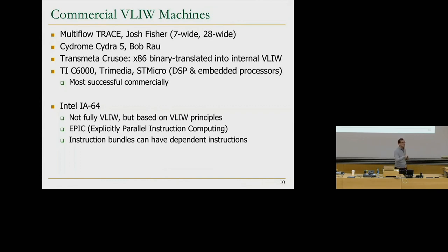The compiler tells the hardware, okay, I'm sending you 8 instructions per cycle, but look, between the 4th instruction and the 5th instruction, there's a dependency. Now the hardware can actually see that, decode that quickly, and it doesn't need to check for dependency. Trust the compiler, and order the instructions based on the compiler's instructions. So it's actually a very neat, interesting idea.